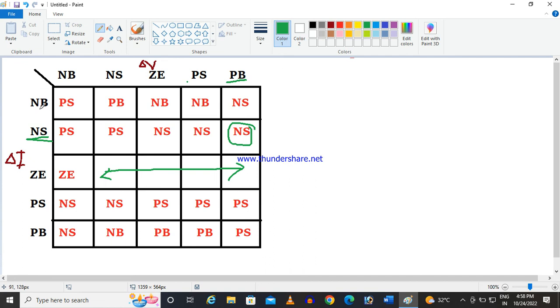If my del I is negative big but del V is 0, then my del D will be negative big. So this is a conventional thing I have taken, but it can be fine-tuned once we do the actual experiment. Okay, so this is all about the algorithm to implement the fuzzy MPPT algorithm.